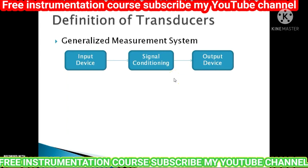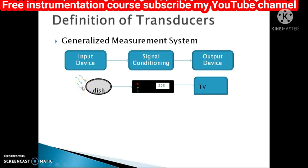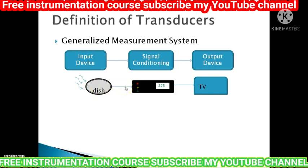Consider an example of the dish connection which you have at home. You have the dish as the input device which gets the electromagnetic signals from the satellite. Then it is converted into some kind of signal which would be understood by the set-top box. Here the set-top box becomes the signal conditioning unit, and then in turn it is given to a TV which becomes your output device. Here the input quantity is the satellite signal which is received by the dish, and it's a non-electrical signal. It then needs to be converted into an electrical signal.